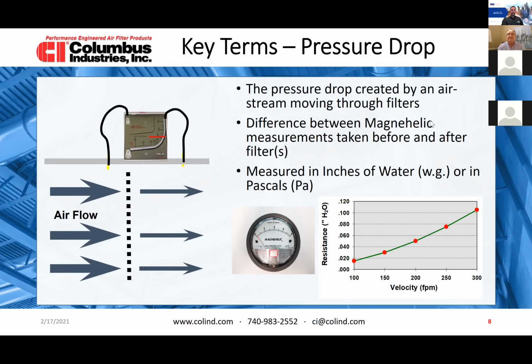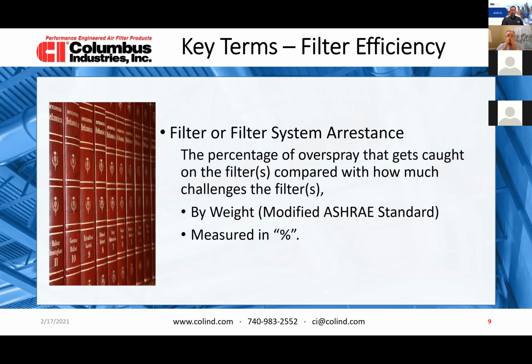And as you can see, for a clean filter, if you increase velocity, the pressure drop will increase as well. So another term is filter efficiency. When we talk about efficiency, sometimes you wonder why you hear efficiency and sometimes you hear arrestance.